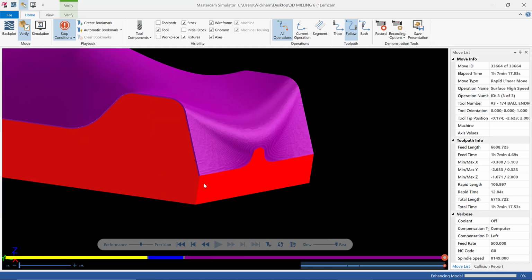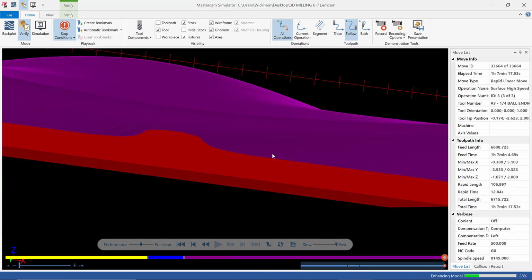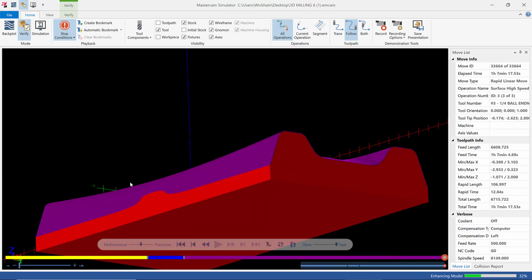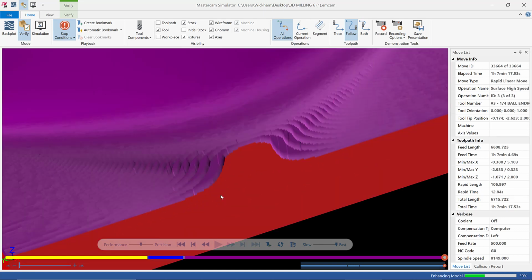It would be essentially, like I said before, trying to machine all this in one. That does help, and it'll help it get a straighter line here. The other way to minimize this is to change the direction of the toolpath. That would work well too, but this looks worse than it actually is in material. Okay. So don't worry about it for this one when you get stuff there, especially if the flat comes up. I'm not really worried about it for these examples.